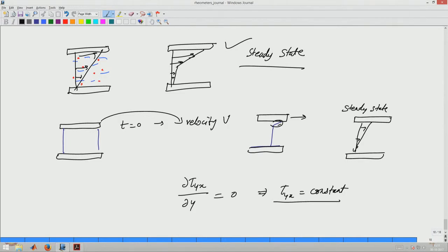There is a class of materials which show density gradients, like the particle gradients we saw. Whenever such gradients are possible, the material shows shear banding, because it overall breaks into a low viscosity and a high viscosity regime, and therefore into a high shear rate and a low shear rate regime.